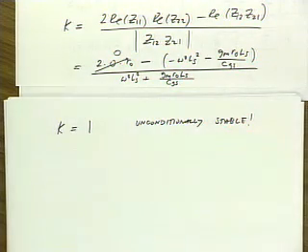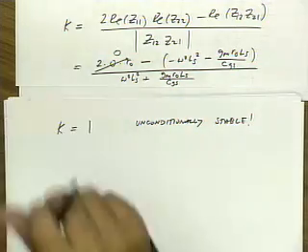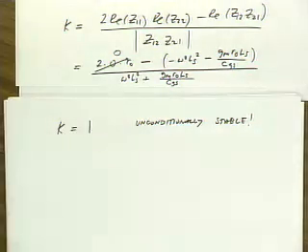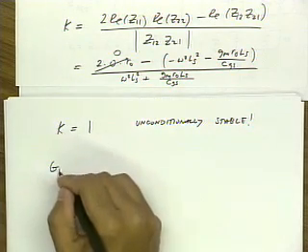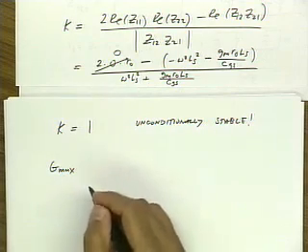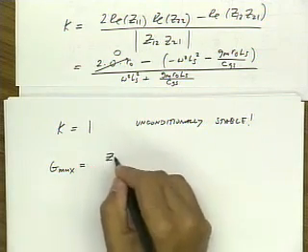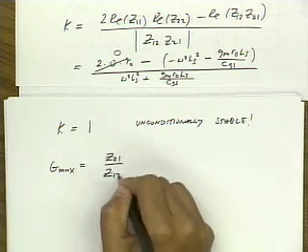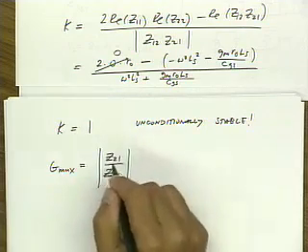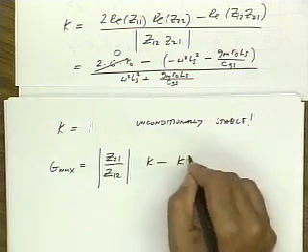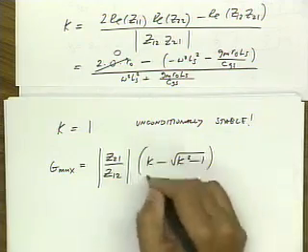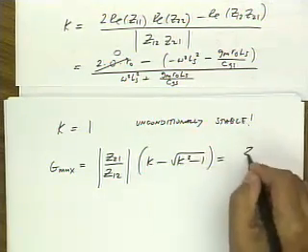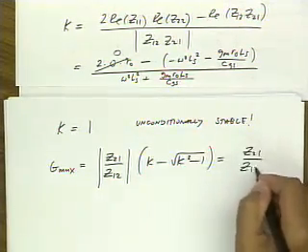That's actually pretty nice. It took our device, which was already unconditionally stable. We introduced feedback, but we found that this feedback can never make it actually oscillate. It's always going to be stable. So now if we look at the expression for the maximum gain we can get from this device, now I'm using Z parameters. It's Z21 over Z12, K minus square root of K squared minus 1. Well, K is always equal to 1 for this amplifier, so it's just Z21 over Z12.